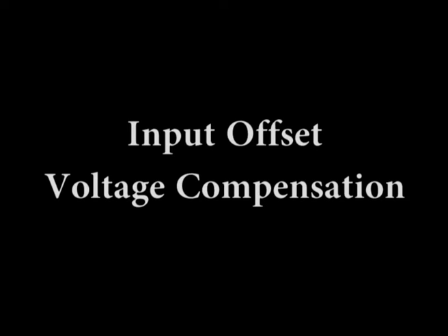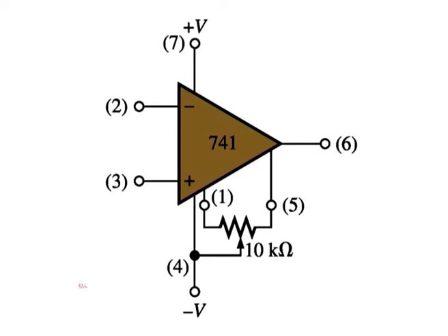Input offset voltage compensation. Most integrated circuit op amps provide a means of compensation for offset voltage. This is usually done by connecting an external potentiometer to designated pins on the IC package as illustrated in figure for a 741 op amp. The two terminals are labeled offset null. With no input, the potentiometer is simply adjusted until the output voltage reads 0.